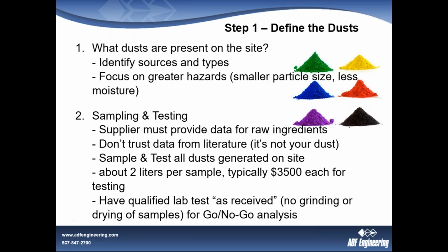Also keep in mind, another of the requirements of NFPA 652 is that anyone who is producing and selling materials that would be considered combustible dust must put on the SDS that goes out with shipping that material, the combustible dust data. You'll need to see the KST, the MEC, and the MIE at a minimum on those SDSs, which means if you're bringing in a lot of raw materials yourself, you may lean on your supplier to get you that data, and that can go a long way.